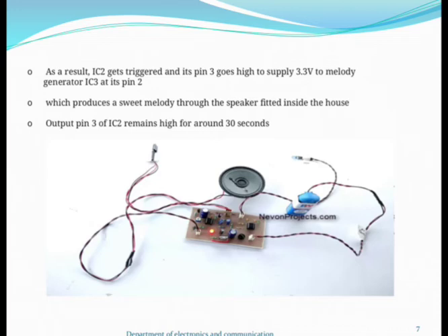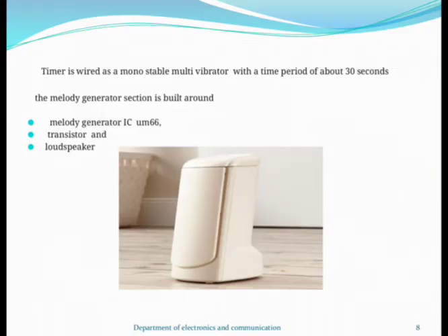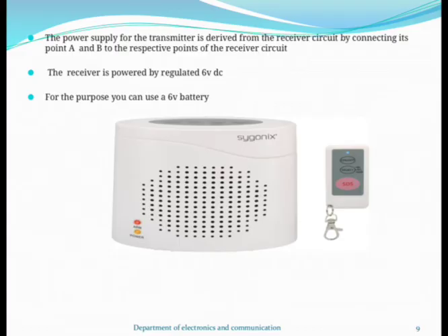The output pin 3 of IC2 remains high for around 30 seconds. The timer is wired as a monostable multivibrator with a time period of about 30 seconds. The melody generator section is built around the melody generator IC UM66, a transistor and a loudspeaker.